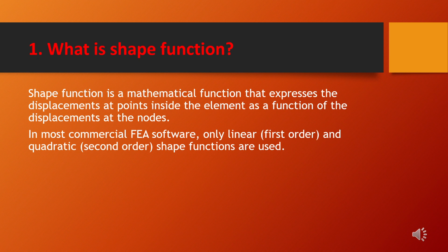First question: what is shape function? Shape function is a mathematical function that expresses the displacements inside an element as a function of the displacements at the nodes. After the solution process, we get displacements at the nodes. How will we know displacements inside the element? For that, we need this shape function. In most commercial FEA software, they use only linear or quadratic functions.